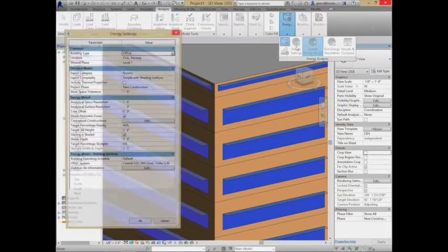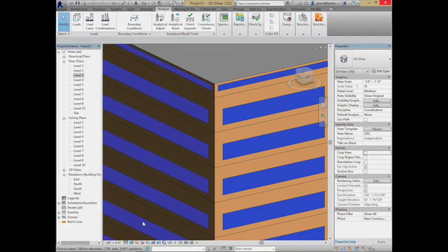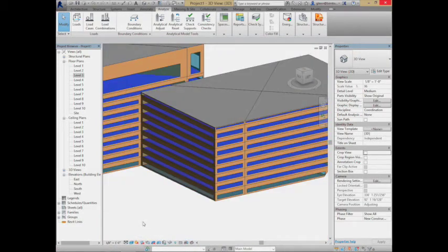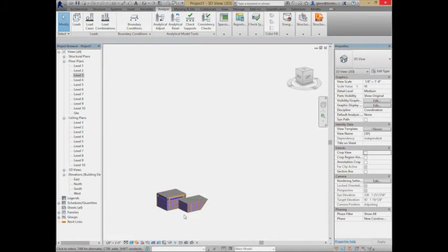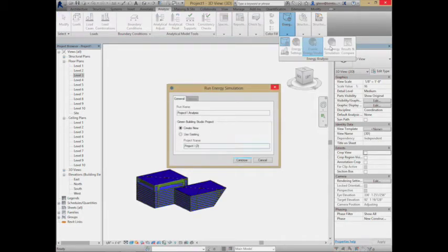But again, I'm going to turn those off because I just want a nice baseline to operate from. So I'm going to say, hey, let's just take a look at a 40% glazing window in Oslo, Norway, so we can figure out really what we can say about it. So for this shape of building and this amount of square footage, let's go through and I'll run an energy simulation. When we do this, it's actually going to send something off to the cloud.